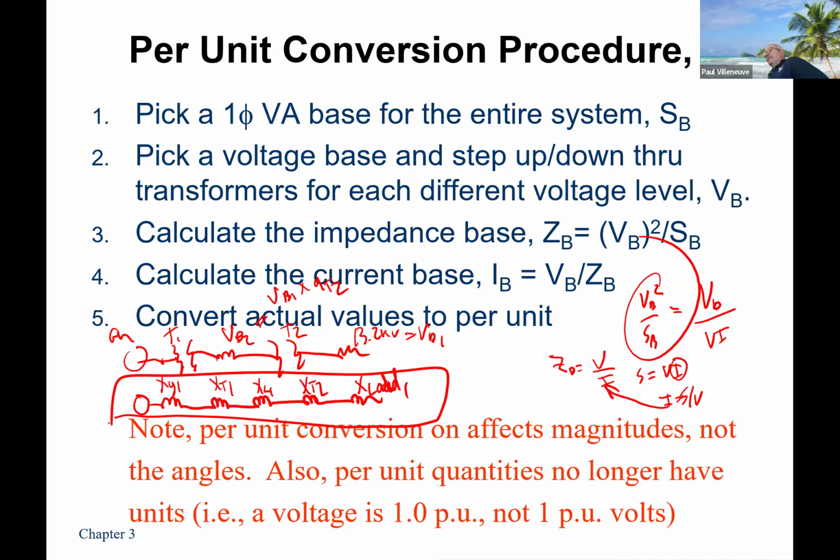Now, how do you know what the nominal voltage is? What's the voltage for the line? The transmission line? Yeah. It's not the maximum voltage. The line voltage, if you're doing it per unit, is you're picking a V base over here, and then you have to calculate your per unit base voltage on the high side of the transformer or at the transmission line. So it's calculated based on the one that you picked.